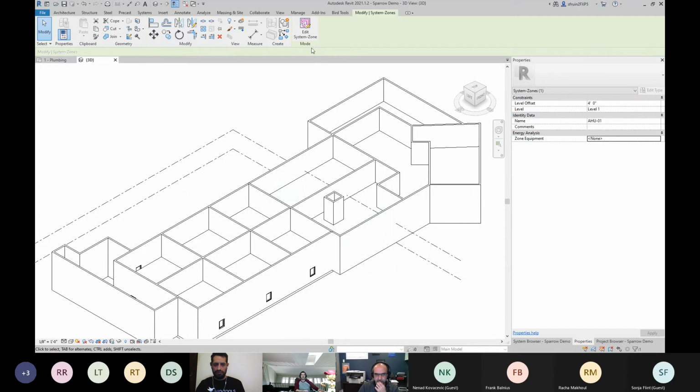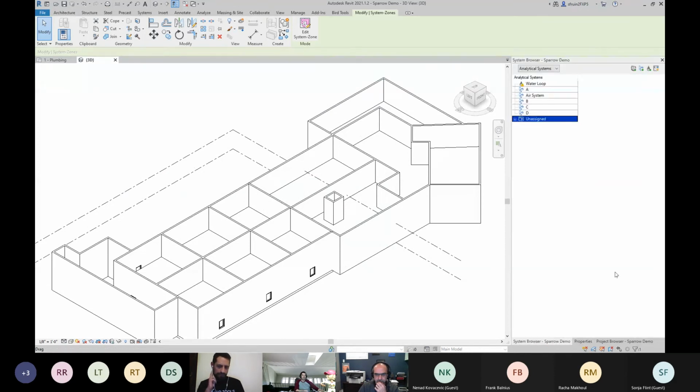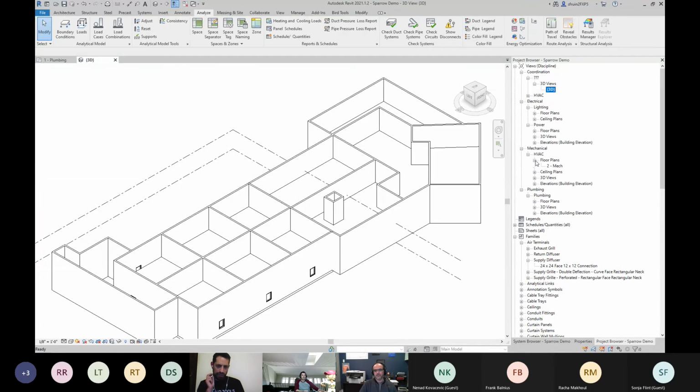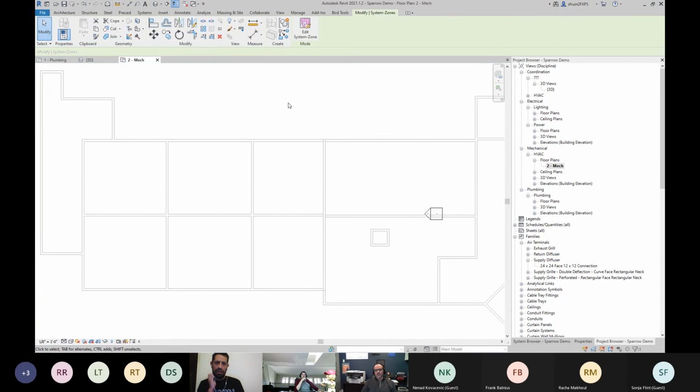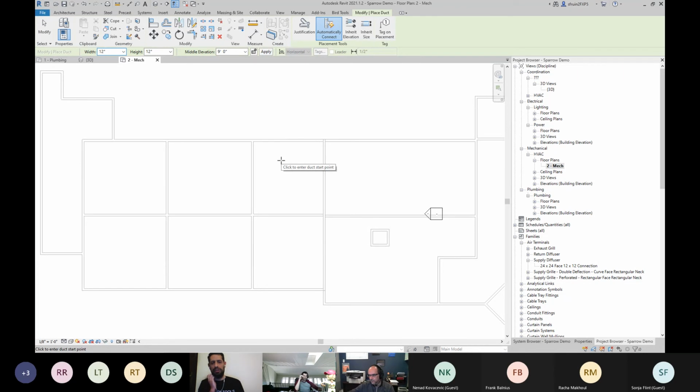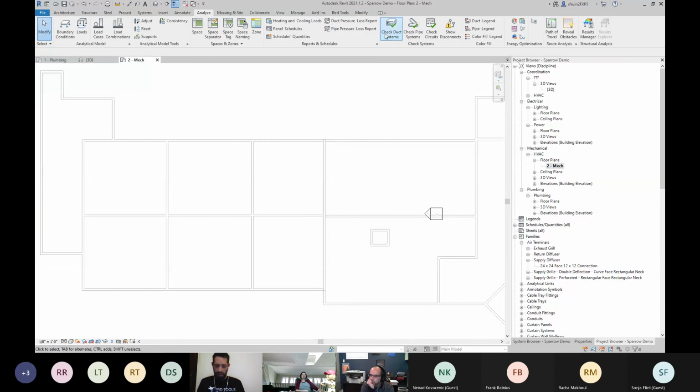Yes, it is possible. It's definitely possible, and definitely not easy, but it's also achievable in way more automated ways than through Dynamo. If you go through the Revit API, you can have it happen automatically as soon as you draw the duct. You can draw your duct and set a splitting distance for your segments, and have the ducts automatically split and segmented. That's something I've personally done as a custom job.